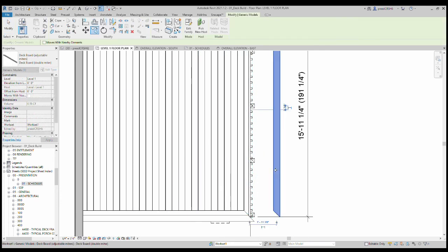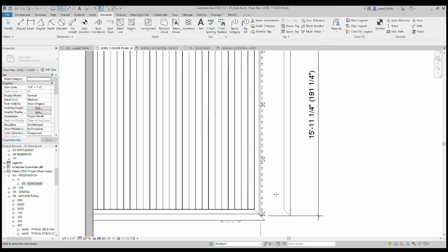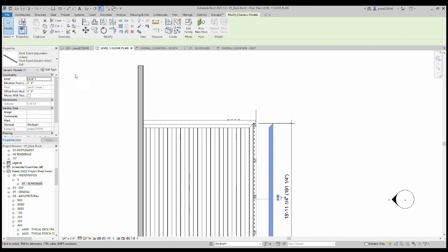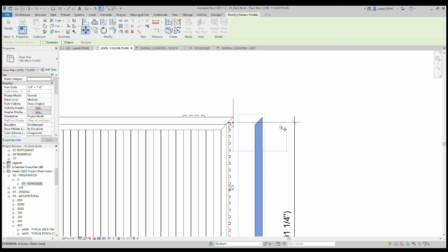Copy this one as well and adjust it, duplicate it. It's going to be 2x6. And I need to actually change the type mark for it to schedule appropriately. See what this distance is from outside corner to outside corner. 16, 7.25 foot. Change that thickness. We'll go make sure it's at the correct level, 2 foot 10.5. We can move that thing over to the corner.